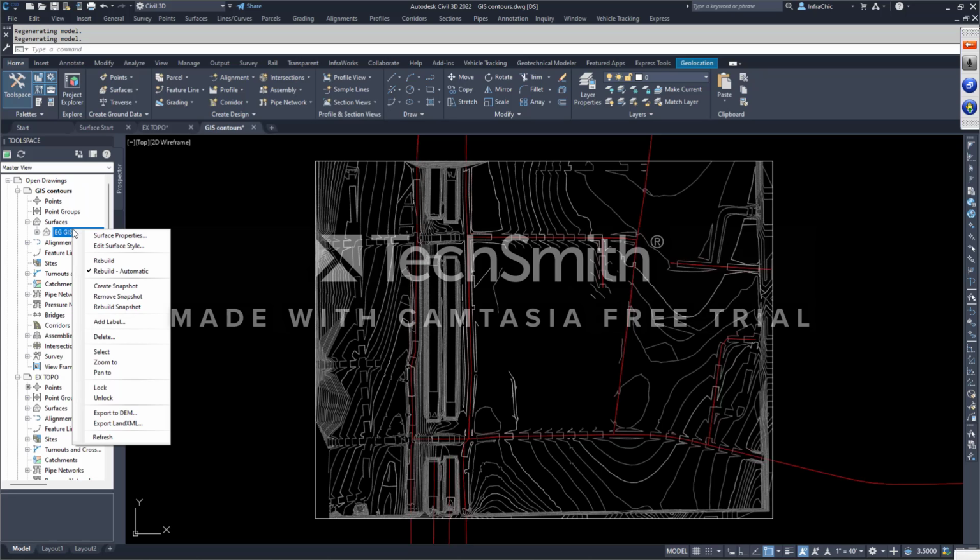and every time they get near something, manhole 5 feet away, manhole 4.8 feet away, manhole 3 feet away, you're at the center point of the manhole. Manhole here, rim elevation, cut fill number. All from that Land XML file. I didn't have to do anything other than give you a Land XML. You get out there and you have fun.